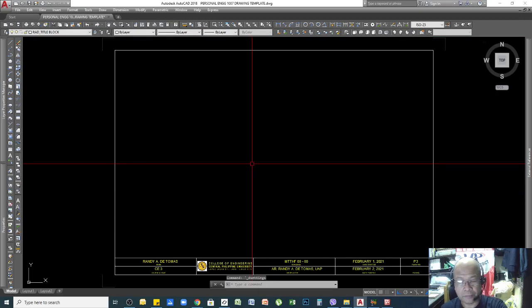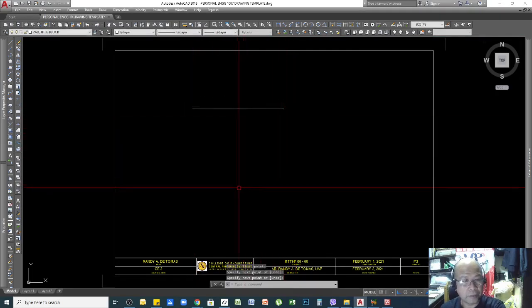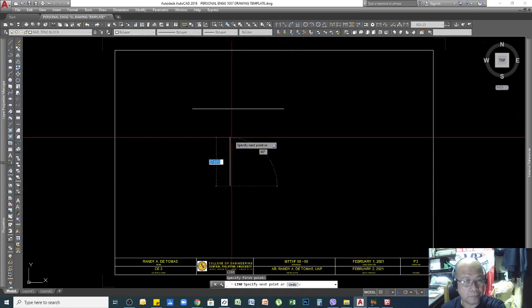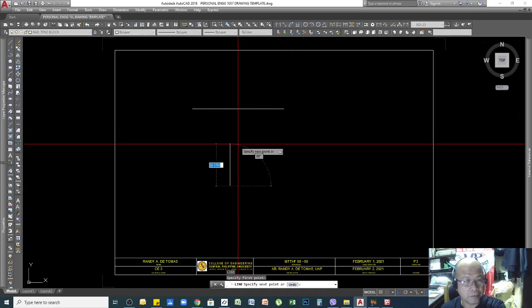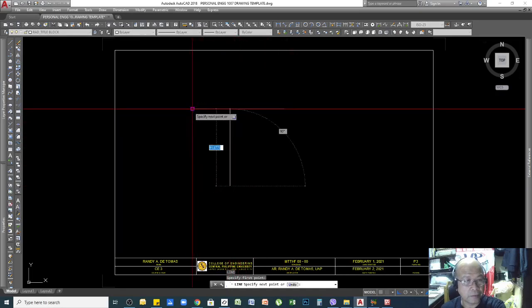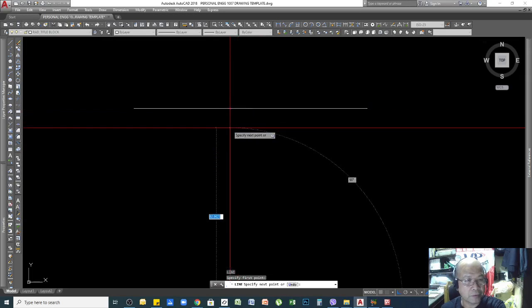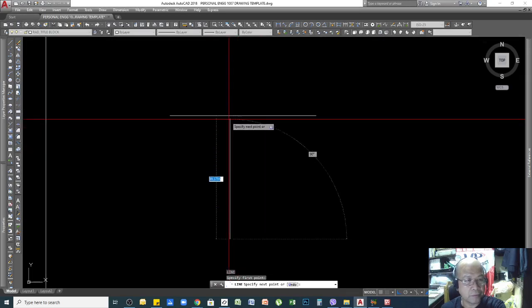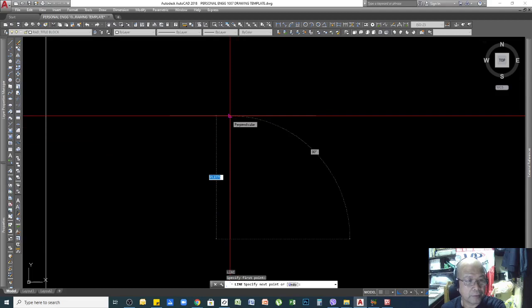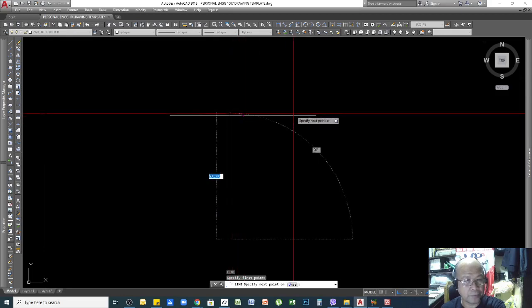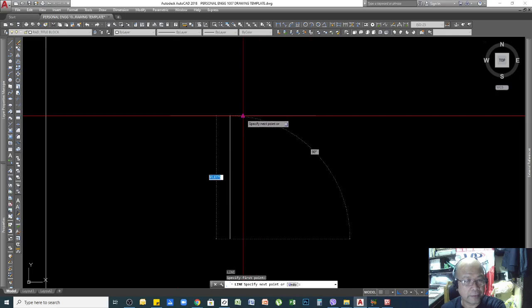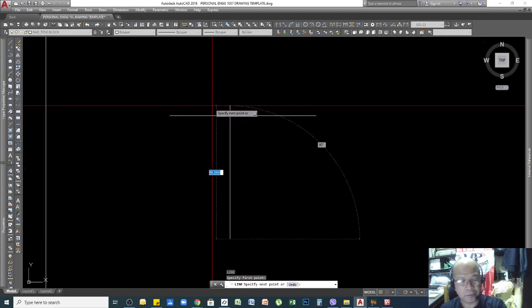And then of course the function of that is that if you like, for example, to draw another entity, you can either select endpoints or like midpoint or perpendicular. So it will depend on your selected options there inside object snap. So like this one, it's perpendicular, but the midpoint of your other line is there. So that is the function.